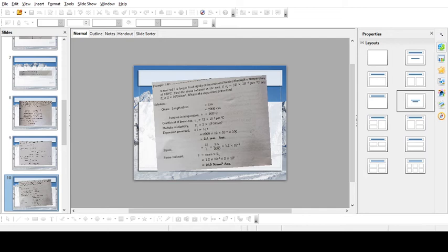So from the equation sigma S equal to 2 by 3 of sigma C, substituting it into the second equation, that is 1.2 sigma S plus 2 sigma C is equal to 2.4 into 200 into 10 to the power of minus 1 into 6. Then you will get the sigma C value as 102.85 Newton per mm square. So the sigma S value will be 68.57 Newton per mm square. Okay. So in this manner, we find the stress in the copper and the stress in the steel bars.